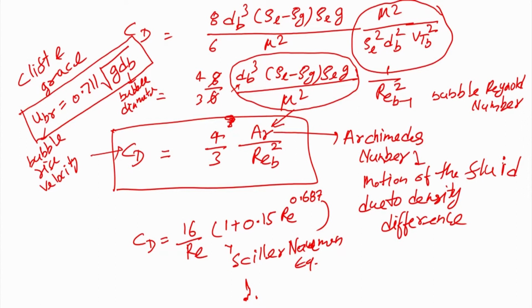You can calculate the bubble rise velocity, and if you know it, you can find what the residence time inside will be. You can also calculate the Reynolds number and use your mass transfer equations to calculate the mass transfer that is happening. You can use the film theory, the penetration theory, or the surface renewal theory, whichever you feel is valid for your case.